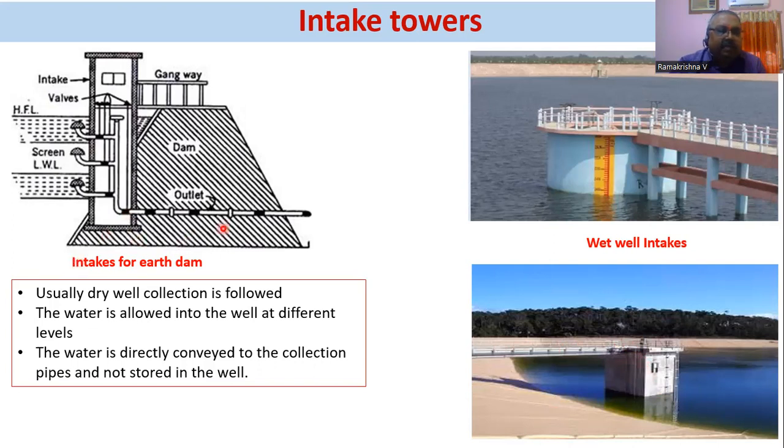The same case applies for earth dam intakes. Usually for dams, where we're collecting the reservoir across a dam, we normally go for a dry well, right? So you're having inlet pipes here, they're connected to a collection pipe, then the outlet passes through the dam and goes out, right? So this is all about the intake towers.